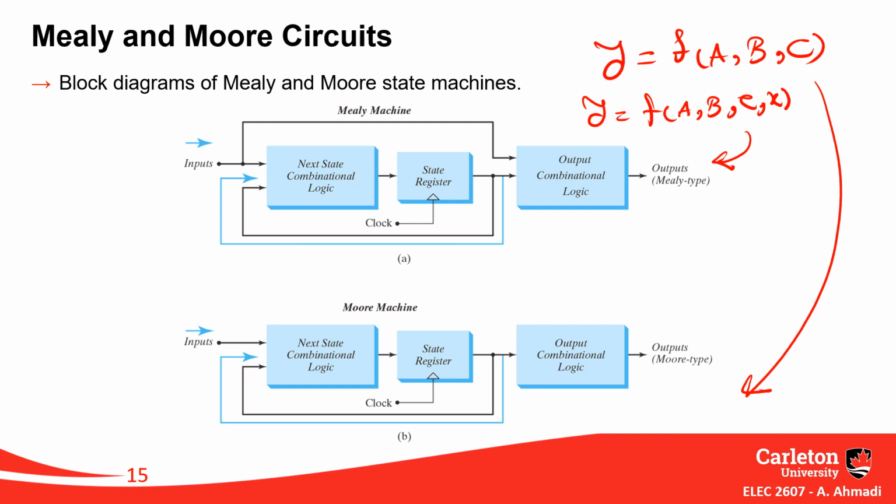Mealy machines are not synchronized. So why did we end up with a Mealy machine? Because we did try to minimize our states. Remember, every Mealy machine can be converted to Moore machine and vice versa. And normally, Mealy machines have fewer states.